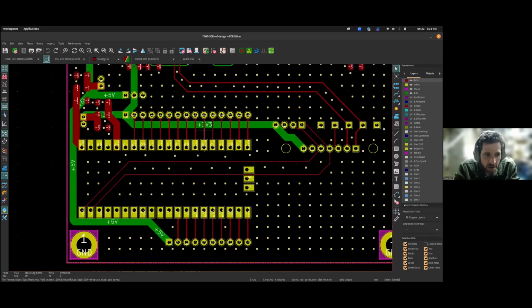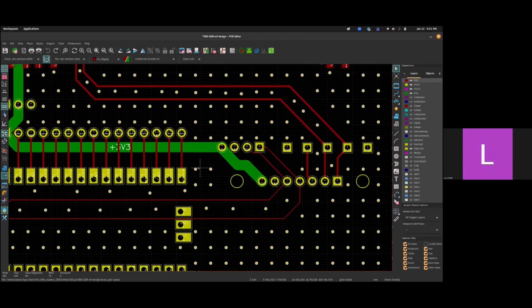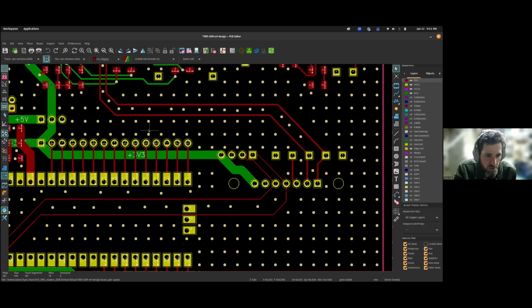So you can see I can have some high-speed digital lines. These are GPIO pins from the Pico that are going to this breakout. If this was a 2-layer board, looking at the bottom layer, I've got my power trace. I would have my power trace running directly underneath these digital lines, and you cause yourself all kinds of problems with coupling. All these digital signals going across these lines would be coupling into your power, causing you trouble. But having a 4-layer board, there are actually 2 solid copper layers between that bottom copper trace and these ones here. So it allows you to get away with a lot that you wouldn't otherwise.